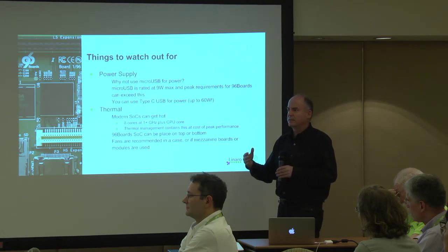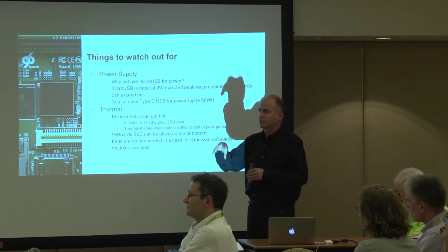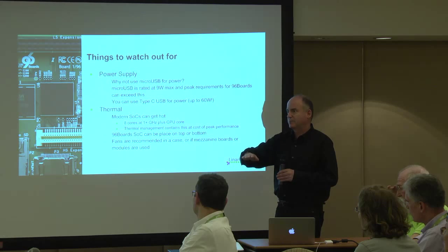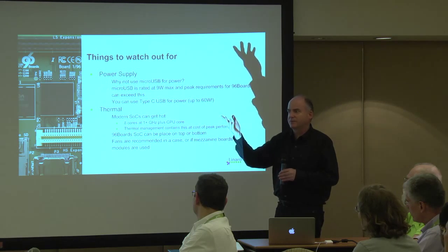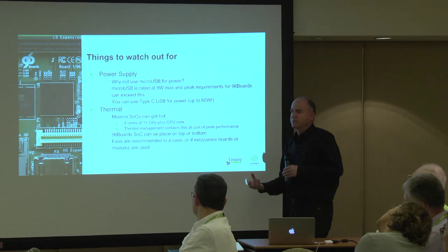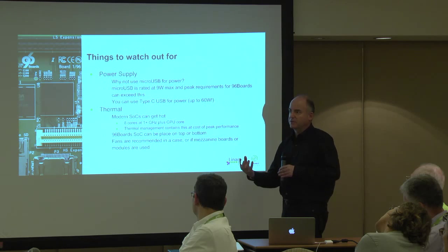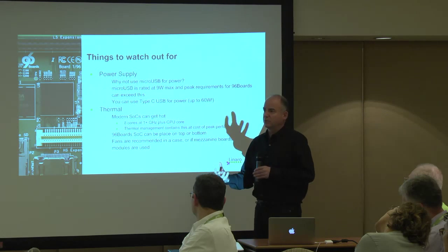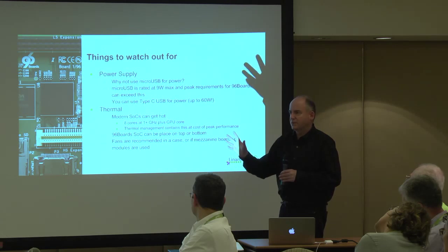If you've got a heat sink or a fan that you want to put on top that exceeds that, it can still fit, and even if it blocks air, because it's moving air itself, that's fine. The other thing you can do is put a heat sink on the bottom of the board: if you mount the SoC on the bottom of the board, you can put a heat sink there. As long as you tell the user what to do, the spec says you can do what you want.